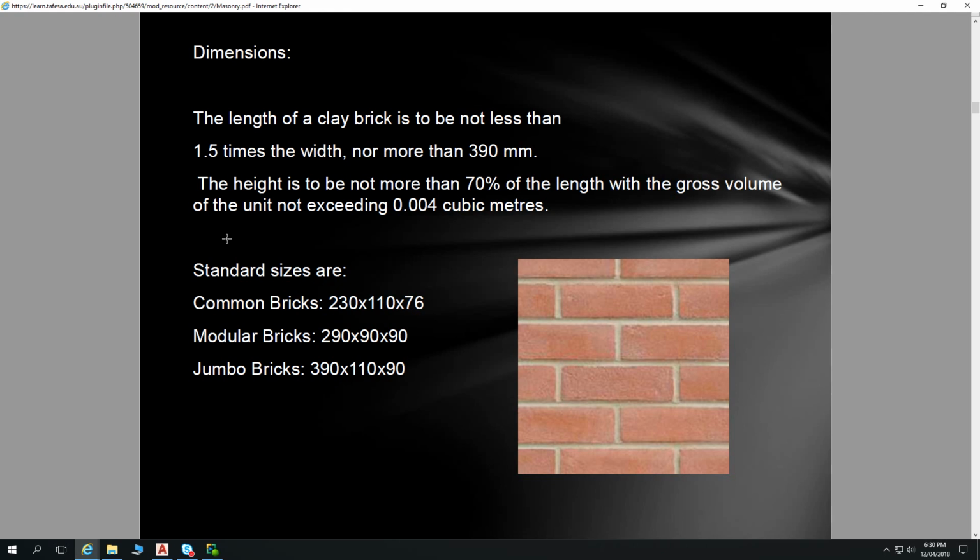Also, we've got some plasterboard in small sheets in 900mm as well, and 1200mm. You know, stud spacing. Standard stud spacing is 600mm. Well, I guess that relates to the plasterboard sizes because you don't want studs out of step with those. But our stud spacing is 600mm. Our rafter spacing is 1200mm or 600mm.